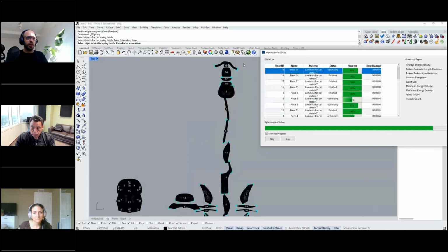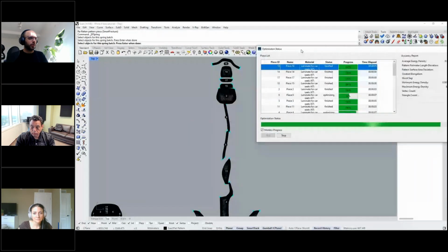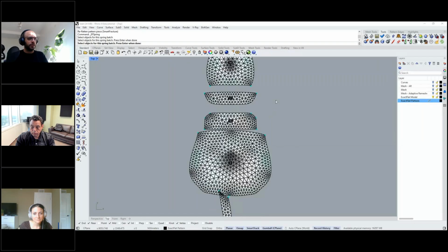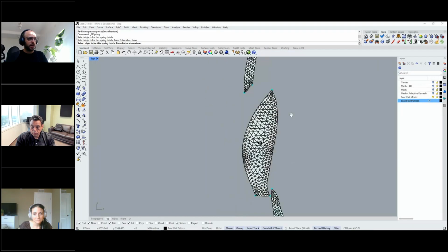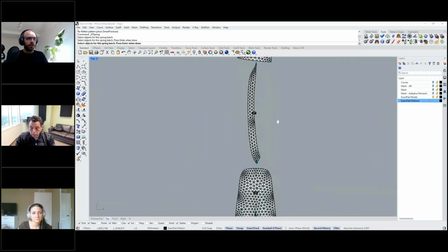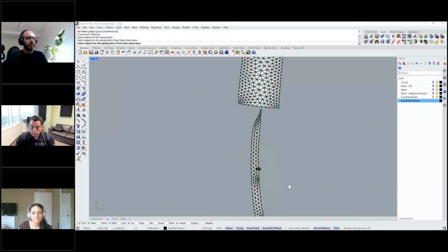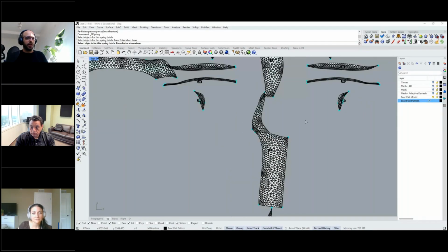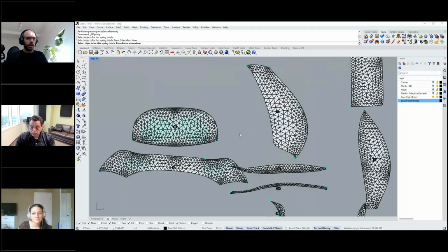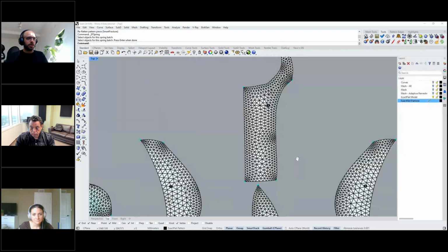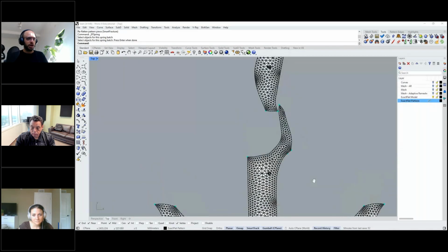This optimization window will show us the progress while our parent pieces are being optimized. So right now, the software is walking the vertices of the patterns to give us the final production-ready patterns. This will give us the best possible fitting patterns with the lowest amounts of strain and sag. You'll notice that as the optimizer processes our pieces, once I hit the OK button to confirm, we'll see that the shape and color of each one of the parent pieces has changed.